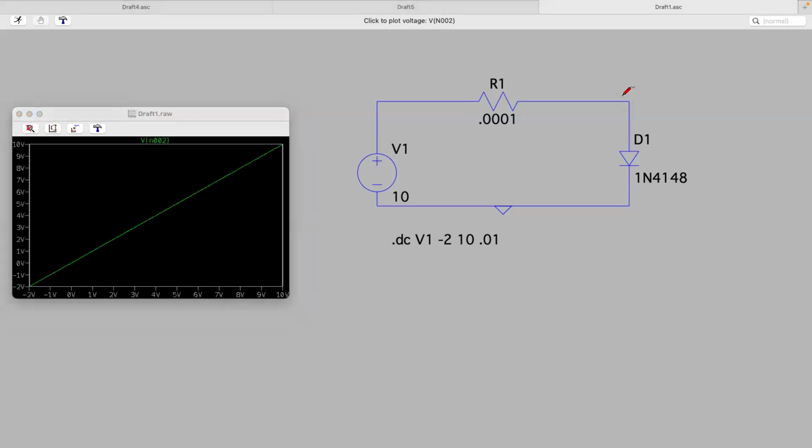So you'll click it. Sometimes it'll give you a hassle. Then you'll see the voltage from your voltage sweep. It goes from -2 volts up to 10 volts. There's really nothing of interest on the x-axis yet, until you click the current. The current probe is literally a device that wraps around your cable. In Physics 196, you learn about the Hall effect. This is literally measuring the Hall effect of the device in real life. Then they just give you a little symbol that's supposed to mimic it.